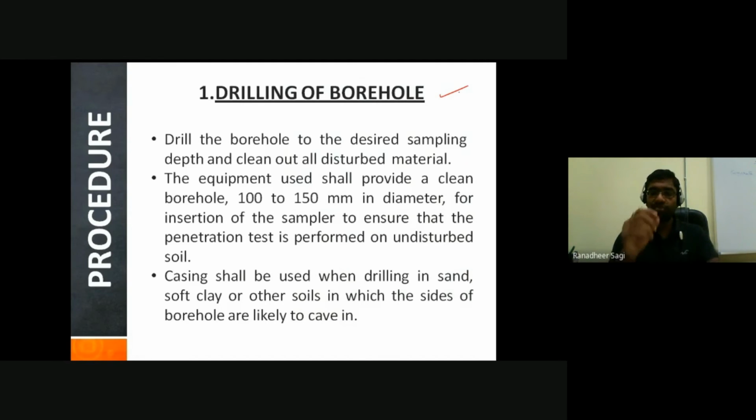Okay. So one thing what we need to understand from this SPT test is, this SPT test will not give the information regarding the soil which is there throughout the depth. Okay, we are not going to find out the SPT value of the soil continuously. Rather, at regular intervals. At regular intervals in the sense, typically SPT test is conducted if at all you want to find out the SPT value of the soil.